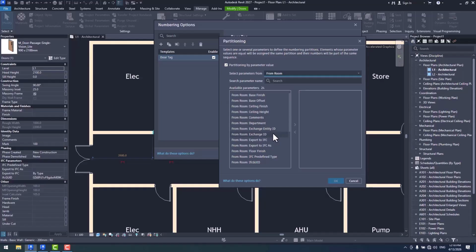Now, let's change this though. I mean, instead of room names, let's go with the height. And this way, the doors would be sorted out starting from the smallest one all the way to the tallest. So then the smallest door would be number 1, and then it goes all the way up from that point.